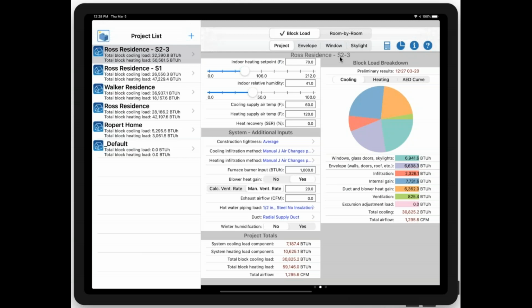I was assuming you would leave it at 0 if it's a balanced system. Let me think about this. It's a balanced system, but you're bringing outdoor air in through that ERV. Yeah, it's something between 85 and 90% transfer of the heat across to the new air. So I guess you're right.